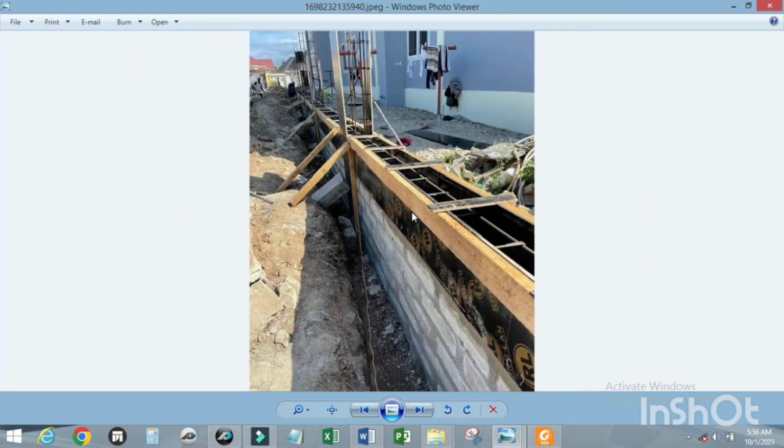This is a situation whereby you don't use this plinth beam or tie beam in all foundations. It depends on structural design, or if the block wall is more than 4 courses, it's advisable to use this tie beam or plinth beam, especially for external walls and some places. So you want to take off the formwork for the plinth beam or tie beam in foundation.